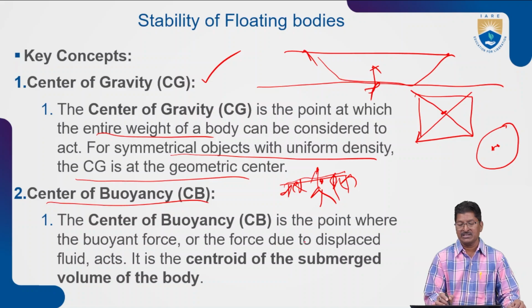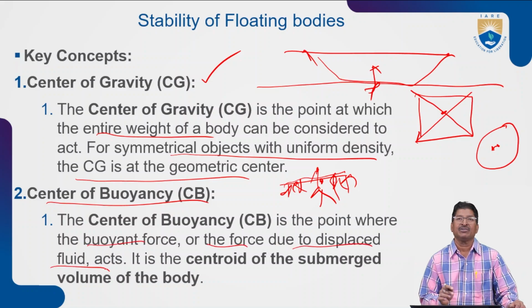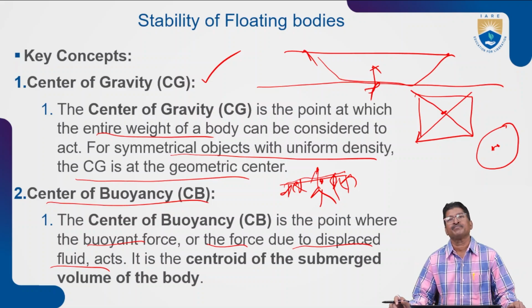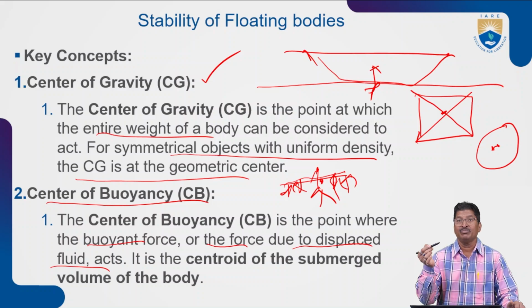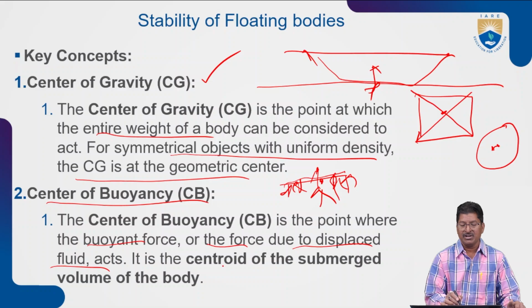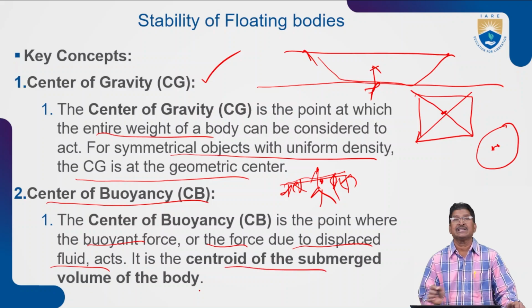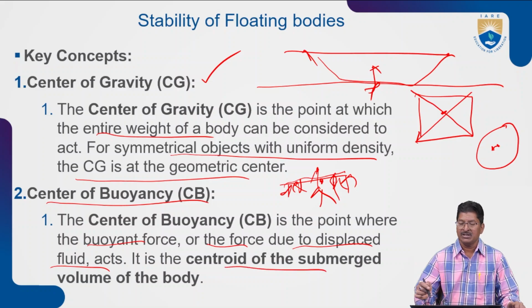What is the center of buoyancy? It's the point where the buoyant force, or the force due to displaced fluid, acts. What is the meaning of displaced fluid? If you put an object into a fluid, some of the fluid is displaced by the immersed volume of that object. So the centroid of the submerged volume of the body is the center of buoyancy. What does it mean?